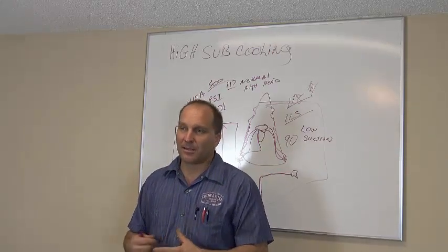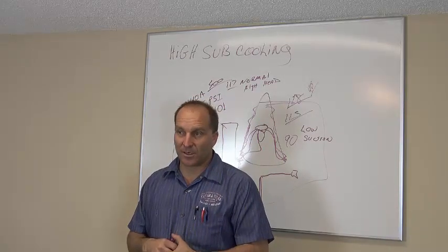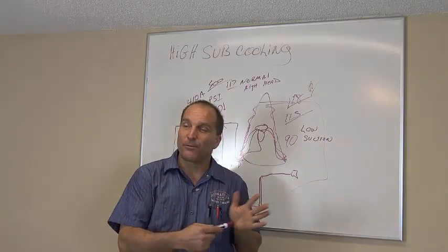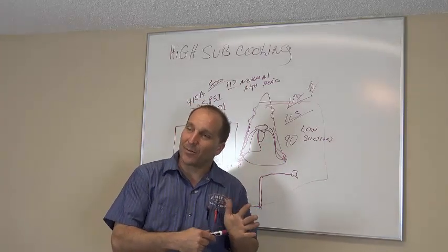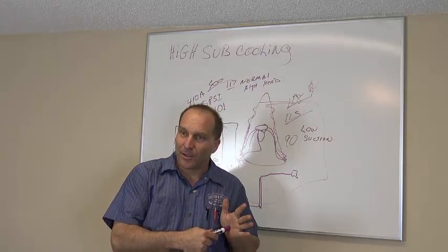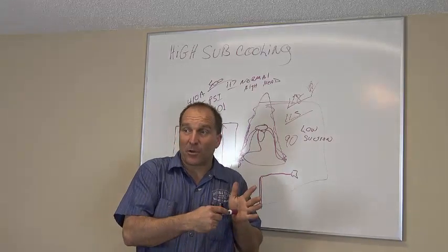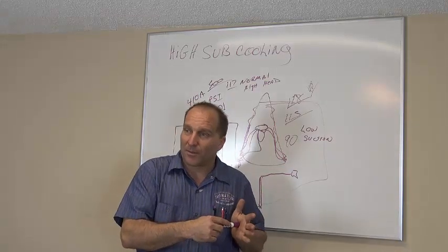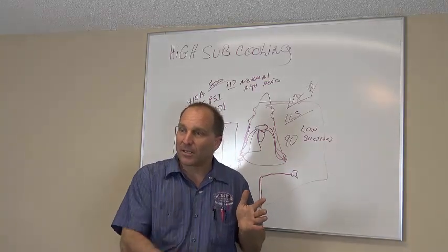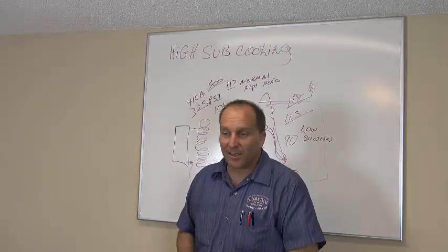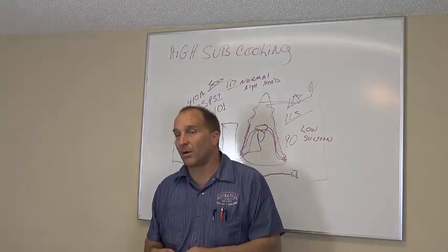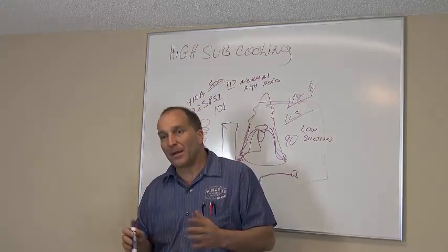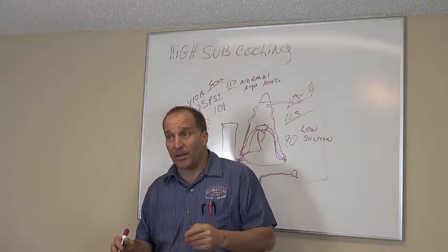Finally, I take his invoices and I start looking up history on these customers. Look, this customer has not had service with us in 4 years. You can't tell me that condenser coil is not dirty. Look, we haven't serviced the system since February of last year. Look, we haven't serviced it in 2 years. I'm finding every single one of them he's going to. He just looks at the condenser coil and it looks not dirty, so he doesn't have to clean it. That is so wrong. If you haven't been to that house in a year, it's dirty. End of story.